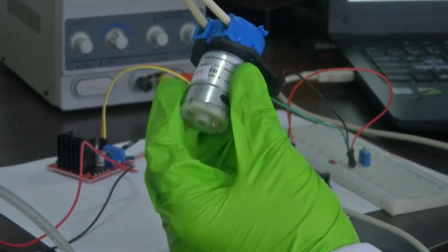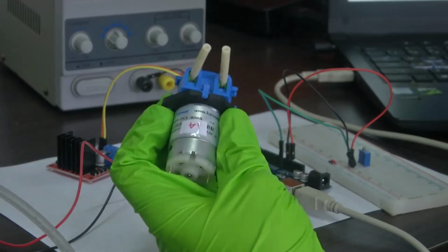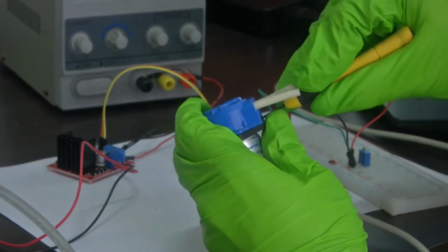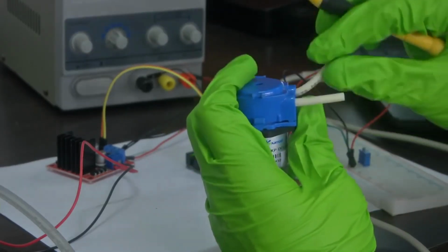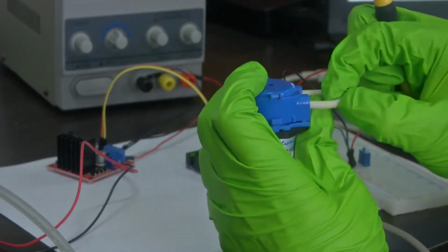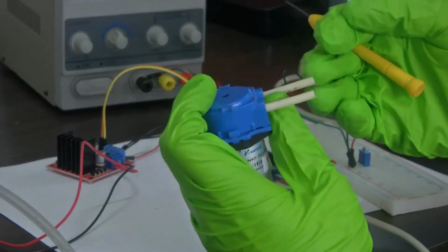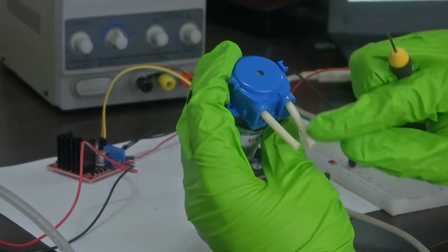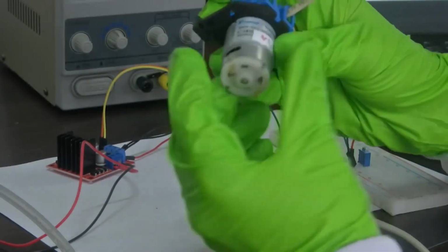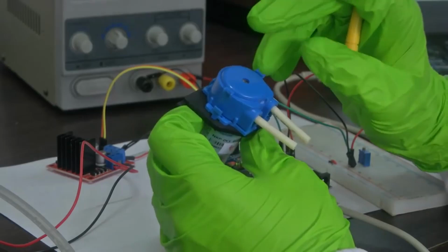I have a peristaltic pump like what you saw in the image previously. This is a small 12 volt peristaltic pump. I will open it up and show you how it looks inside. This is the flexible tube that we talked about. So this will be compressed. If we give the input fluid here, that fluid will be sucked and pushed in, and the output will come through this tube. The output will come through this tube and the input through this tube, and you can see that there is nothing but a DC motor here. The DC motor is what is rotating that roller that I have shown here.